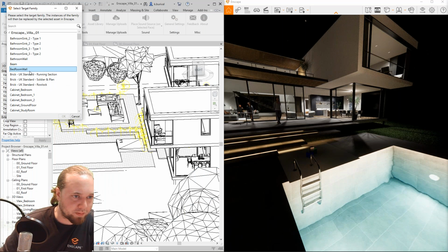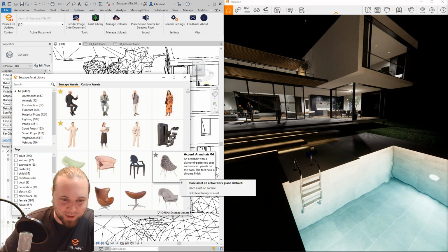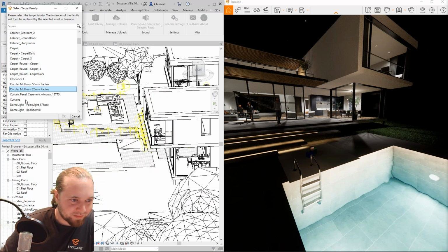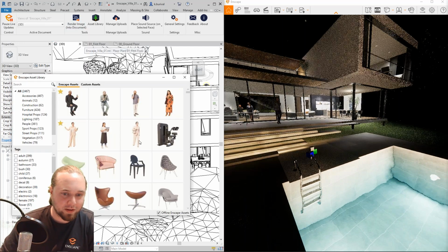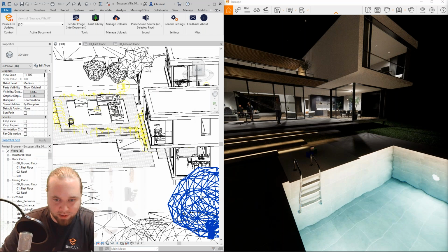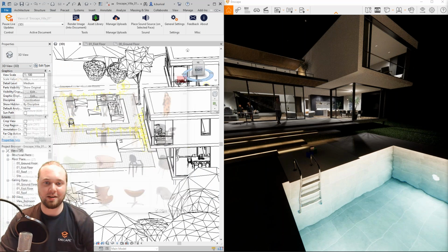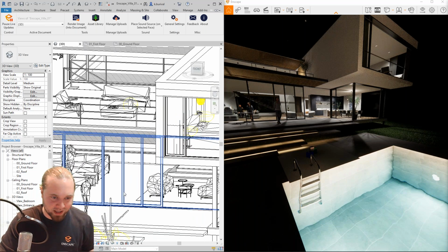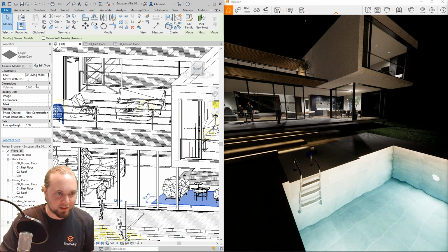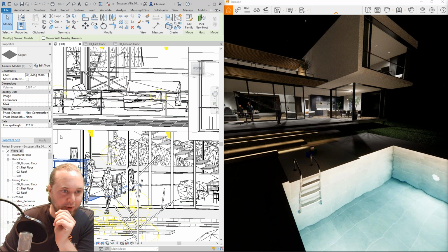So connecting this chair here, link Revit family to asset. Let's go with wall, for example. Yeah, I thought so. We can replace it with a wall. I get that. Let's go with the carpet then. And let's click on these three dots again, link Revit family to asset. Well, you could go into the family we've just taken, the carpet family, and remove the custom parameter that has been added, but there is no functionality built in right now to disconnect it again.